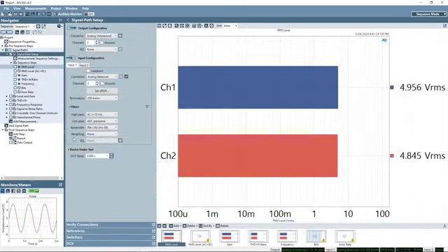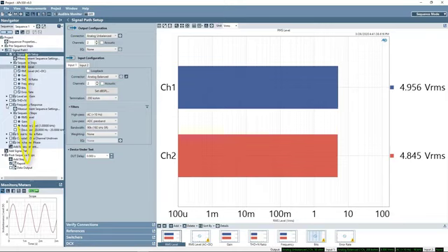The navigator displays your sequence, which is a list of signal paths, measurements, and results that will be executed from top to bottom when the sequence is run, thus automating the test system. The hierarchy is the APx500 project file, sequences, signal paths, measurements, and results. An APx project may contain multiple sequences, executing multiple signal paths, each with their own settings, measurements, and results.